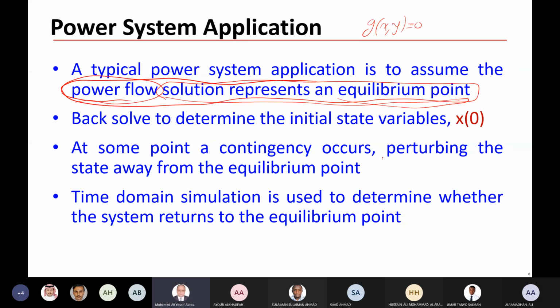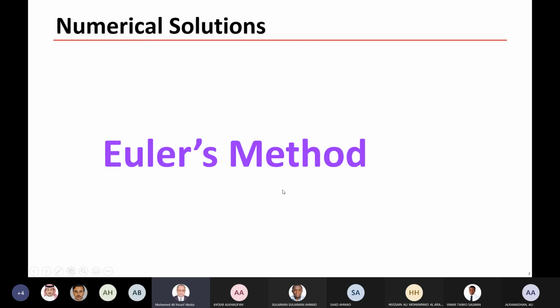Of course, if you solve the swing equation numerically, and you get delta as a function of time, you will see delta oscillating as such, so you can judge whether the system will regain its stability or will be unstable, and what the equilibrium point is at the end. So solving the swing equation gives you an indication of the system stability.